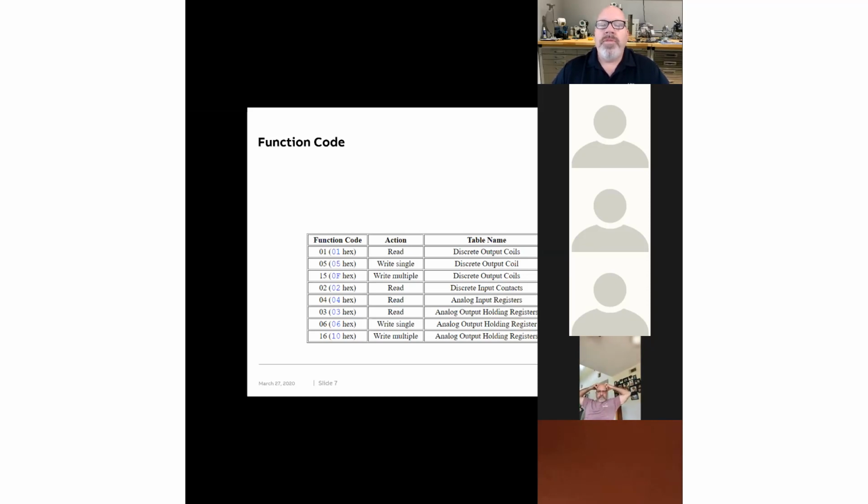So with Modbus, we typically have a sequential list of registers. If I have coils, let's keep it simplistic, and I have a pump start, a pump stop, a valve open, a valve close, 4 registers, I can ask for the status of all those registers. So I would say, okay, slave ID number 1, I want you to function code, we want to read multiple registers.